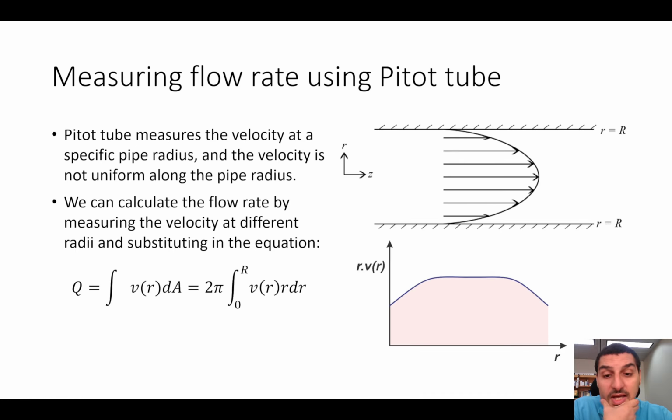Usually the information that we have for a case like this is all tabulated data. Like, at this radius, this is the velocity; at this radius, this is the velocity. So we don't have the velocity as a function; we have the velocity as numbers. For this case, one thing we can do is the graphical integration, and this is very simple. What we see here is equivalent to this.